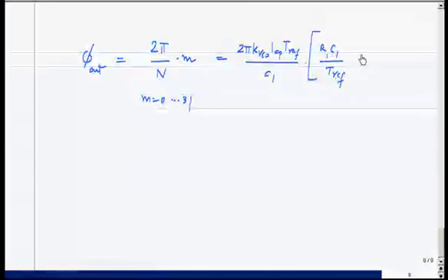We have R1 C1 by Tref times single summation plus the double summation of the charge pump output. So we have to choose m, and this equality has to be considered carefully. It won't be exactly equal because the left side is quantized. We have to basically choose the nearest value, okay.